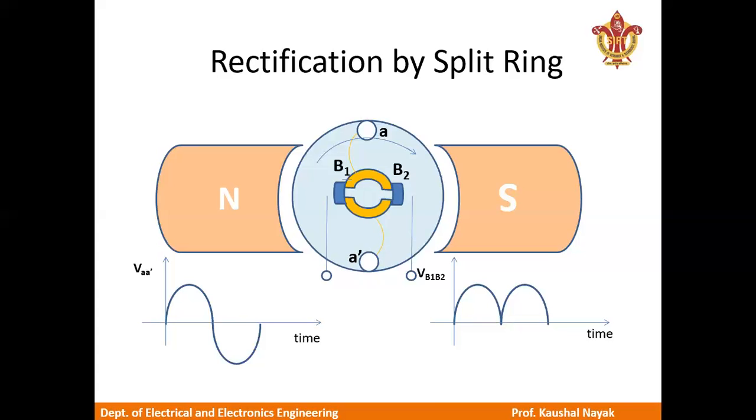In an actual DC machine, there are a large number of coils and slots, and the number of poles is usually greater than 2, except for small DC machines. Therefore, the DC machine illustration as given differs from a real machine, but it serves well in explaining the commutator action.